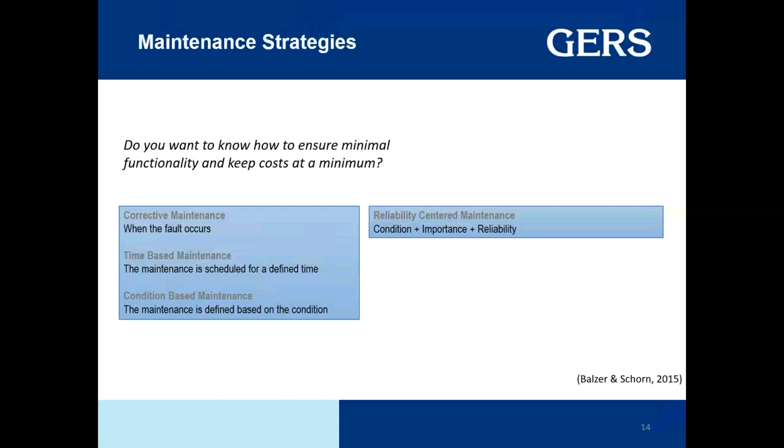The second one is the time-based maintenance. What does this concept mean? Basically, we are able to schedule a maintenance, maybe 1 week, maybe 2 months, maybe 1 year, and it depends on the experience that we could find on the asset's operation, and even the specification from the manufacturer, among other criteria that we could find when we have a scheduling on the time-based. This is one of the most commonly used methods for the maintenance, when we have a period scheduling for the maintenance.